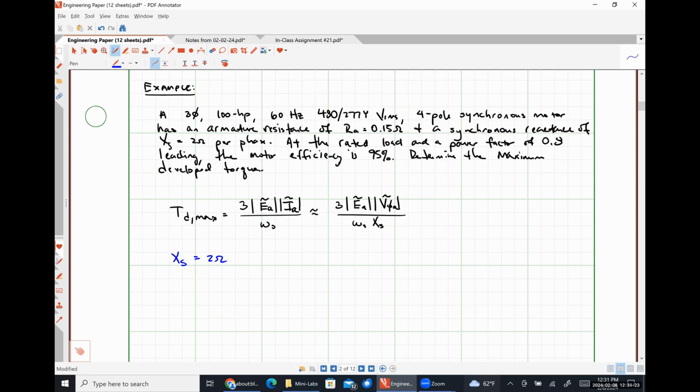So we definitely have at least that part of that second relationship. I think we have another part of that second relationship as well, though, okay? That V_phi_A is the Y-connected voltage that's appearing at the terminals of our motor. And since we were given the rated voltage and we're told the device is effectively working at rated quantities, I think we can say pretty safely that the magnitude of V_phi_A is 277 volts RMS.